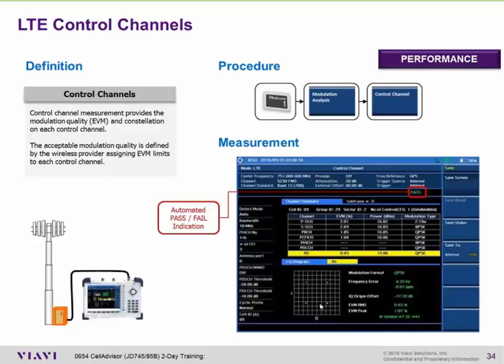Now, to take me to a good sector, I serve by investing time looking at known good signals. That's because when you're investigating a problem, it will be more obvious what is exactly out of place. So I took them to a good sector to show them the SINR values, the dominance, and what I was able to do by pointing a directional antenna right at the known good sector. I then asked them to take me to the worst performing sector, and sure enough, the SINR values were not good, error vector magnitude values were not good.